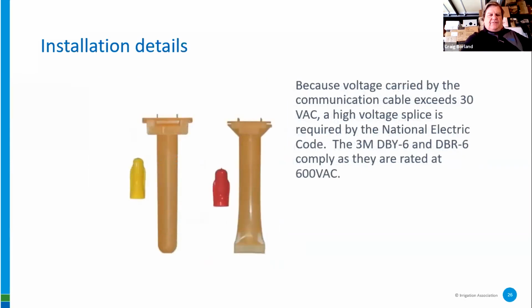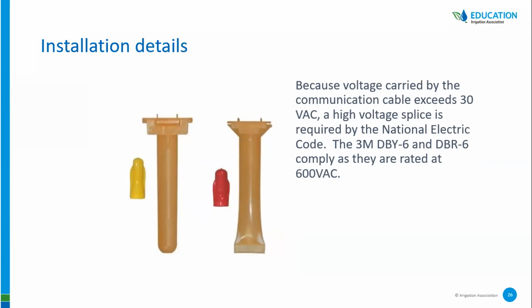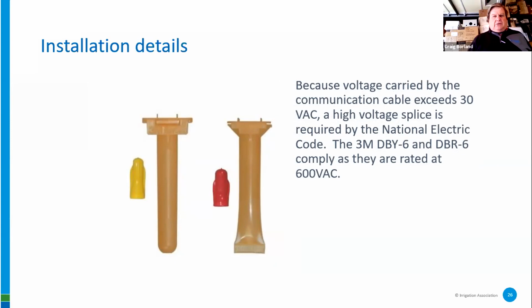You must use a device like this one, where it's brown in color or light blue in color, which has the voltage rating on it for higher voltages. There is a huge problem with people out in the field where they use wire connectors and they're not the proper voltage. Does somebody have a question?